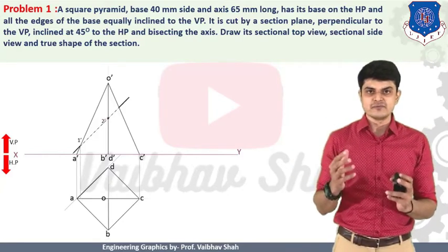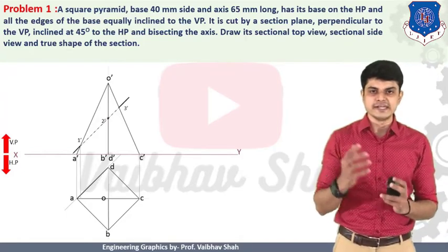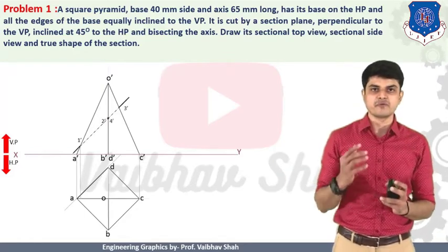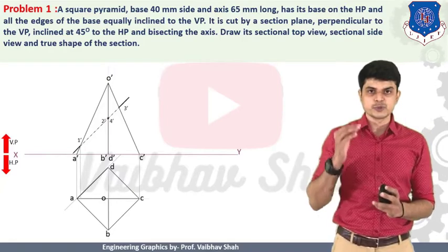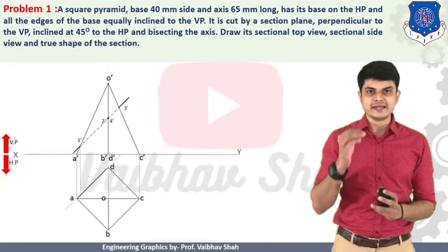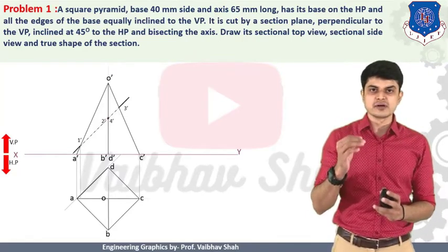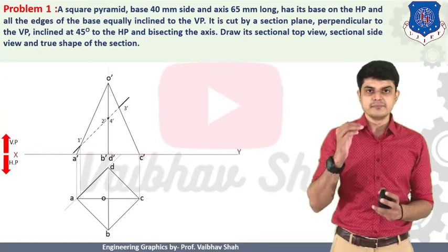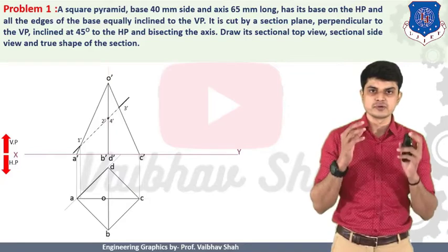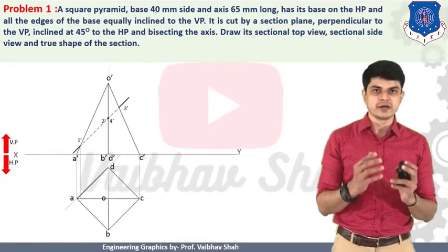Then after B, what comes? C. So O dash C dash will give you the third point, which is 3 dash. And then we come back to O dash D dash, and we will have the 4th point. Always remember, you should give your cutting plane numbering in alphabetical order only. If you make a mistake in placing your numbering, you will have an incorrect answer in your examination. So always remember, you should follow a certain pattern while giving the numbering to your cutting plane points, right?